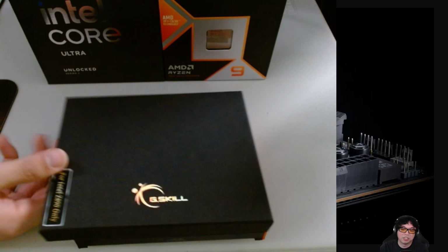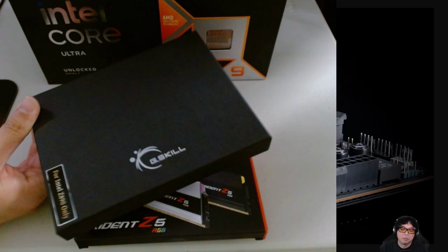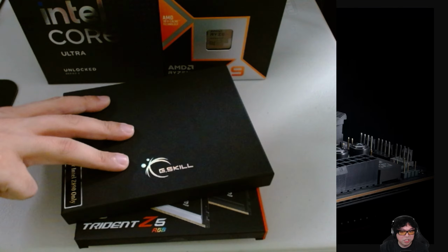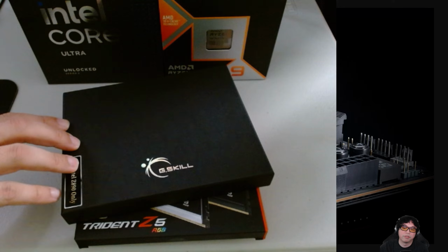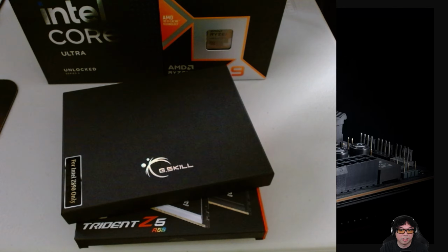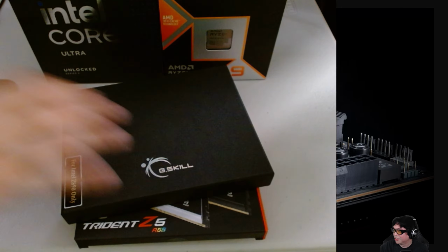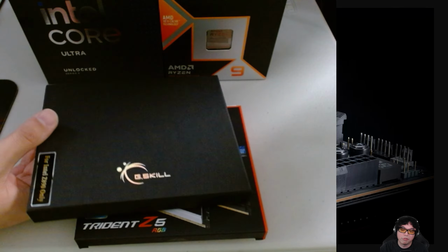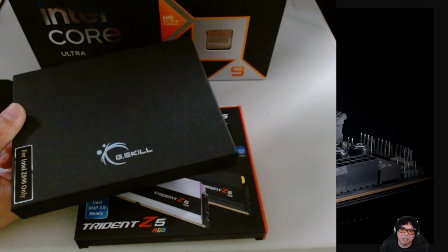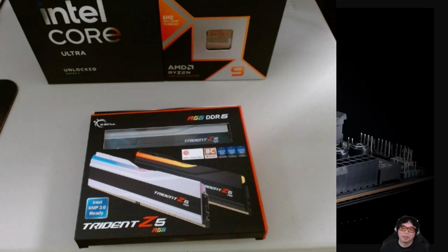We have not tested 4 sticks successfully yet because I have to get a second kit that works, but I can tell you that the 2 sticks, so 48 gigabytes total, so 2 times 24 at 8200, works flawlessly on my Z890 Maximus Hero. So it's basically plug and play, and it just straight up works. I did MemTest86, it did a full pass, a 90-minute test, not a single error. Now, the other memory kit had a ton of errors within 10 seconds, so that one I had to send back. But we will test 4 sticks in a video in the future. I may actually make a video with just the 2 sticks, just to get some content on this topic. But that is a look at CUDIMM.